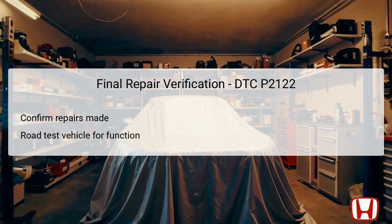Once all necessary repairs have been completed based on the troubleshooting steps, it is essential to conduct a final verification to ensure the issue has been resolved. This involves confirming that all previously identified faulty components, replaced or repaired, are functioning correctly, such as the APP sensor or wiring where applicable. Following component checks, a road test is necessary to assess whether the vehicle exhibits normal throttle response and that the check engine light remains off.